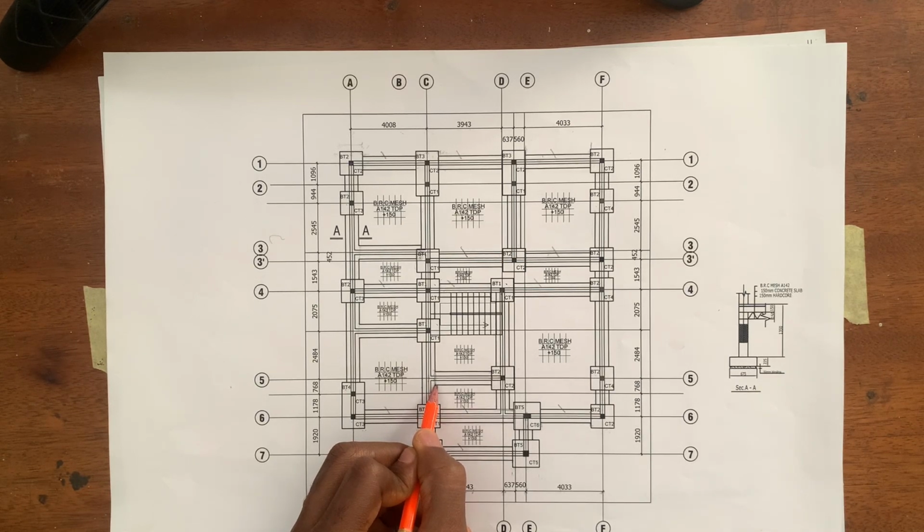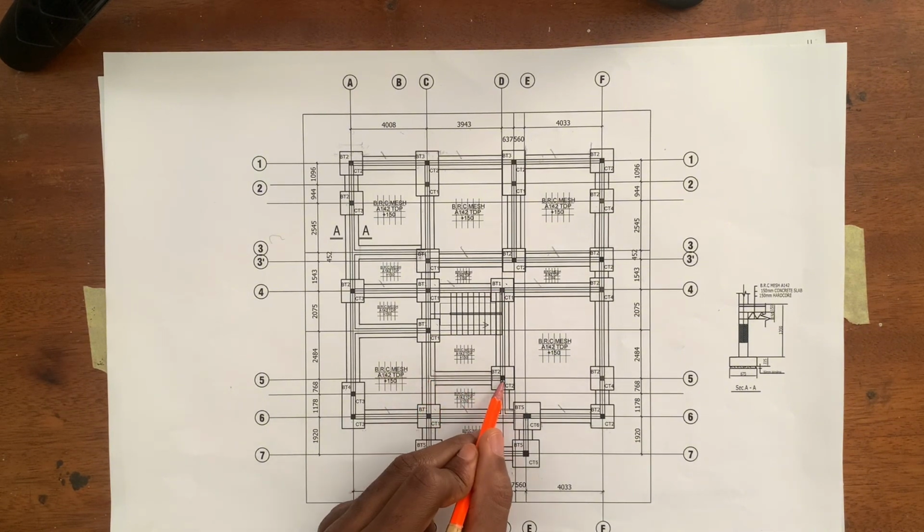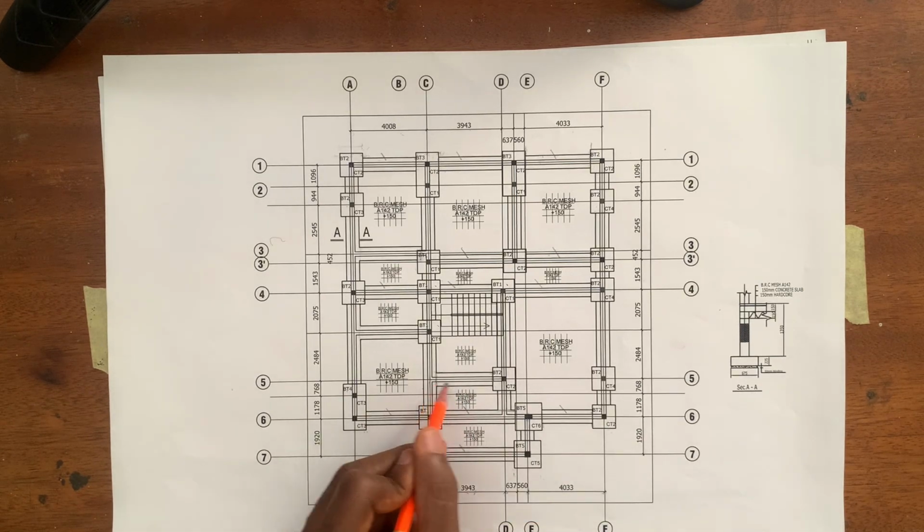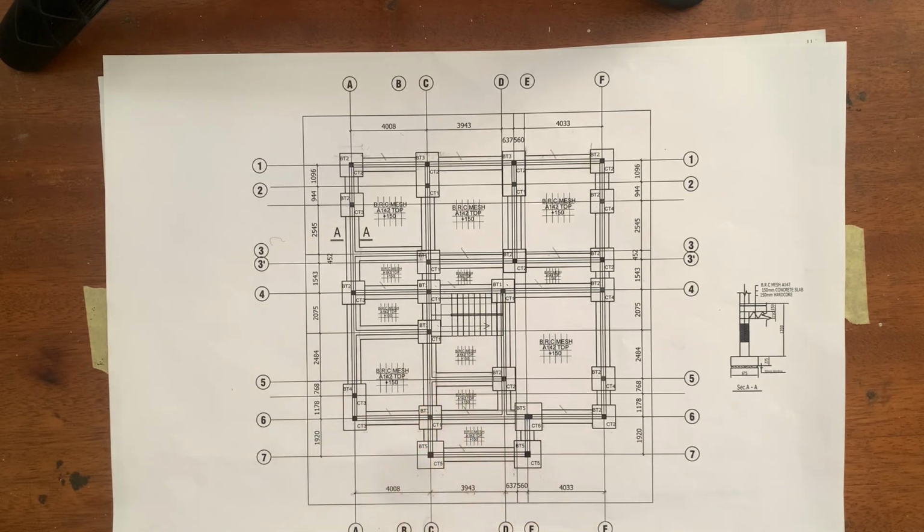So you know that the dimension from this midpoint down to the edge of the trench is 337.5. So you can minus this half and half of the length of this base type 2 from the distance of this midpoint, which is 3,943, to get the distance of our trench. So let's do that.